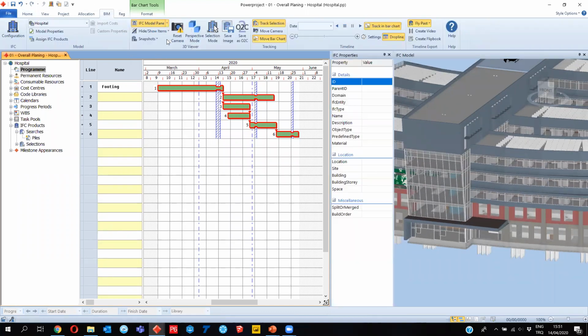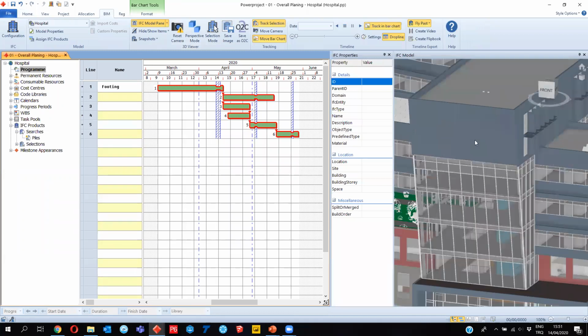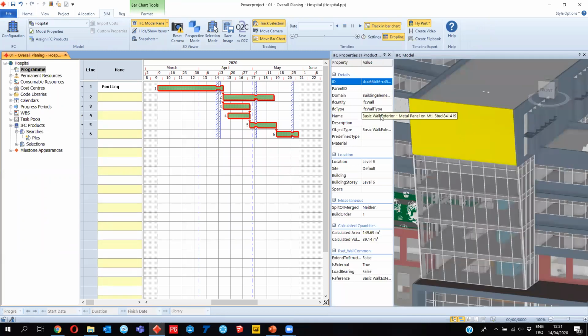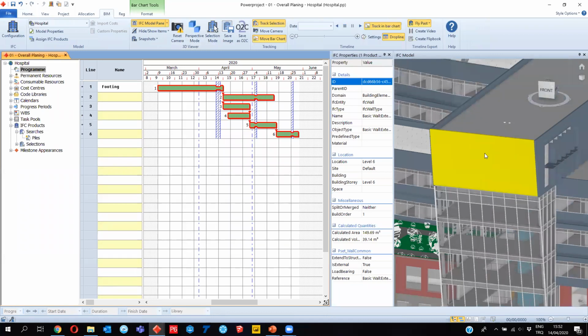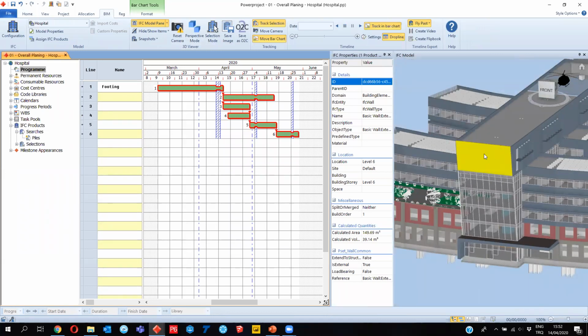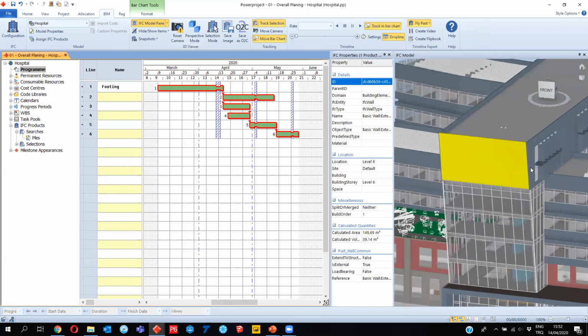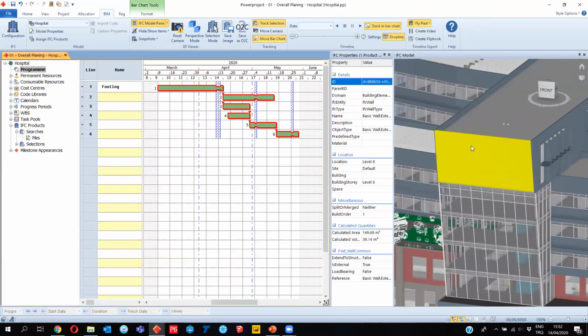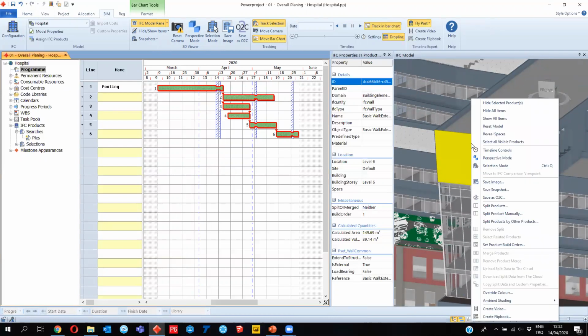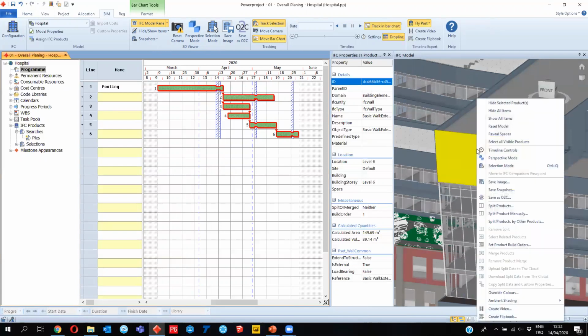Let's open our properties pane, and you see here an exterior structural wall, and you can see its quantity values here. I can also use this design from the design firms or design trades as useful to my schedule. So let's assume that I want to pour this concrete wall in two different times. So let's right click.